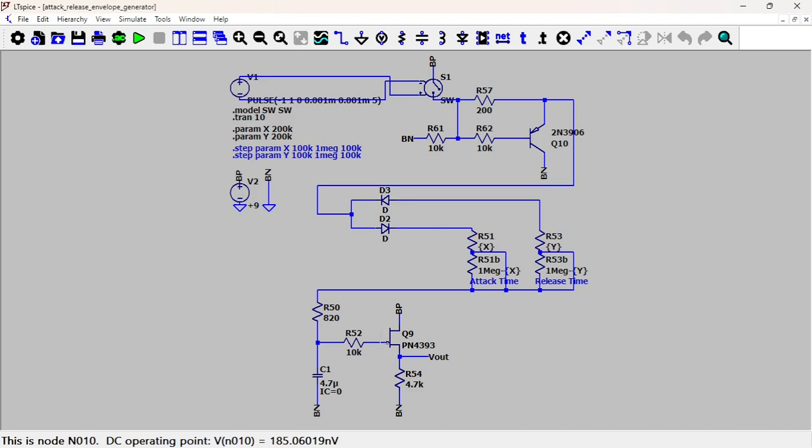And on top of that, it's a unity amplifier. So the Vout you would get if there was no load is the same as the Vout you can get if you put something after that. So again, this is a common drain JFET amplifier. It's very similar to the common collector BJT amplifier, aka emitter follower.